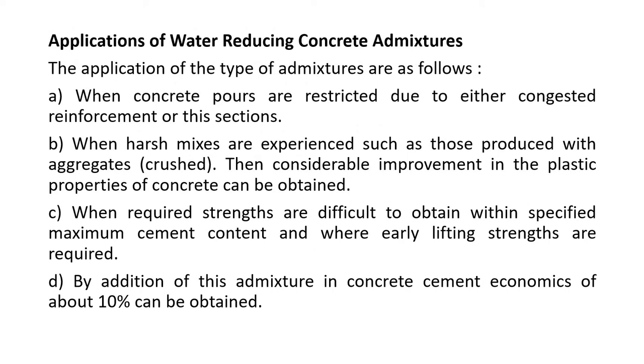Applications of water reducing concrete admixtures. The applications of this type of admixtures are as follows. When concrete placing is restricted due to congested reinforcement or thin sections, when harsh mixes are experienced, such as those produced with angular aggregates, then considerable improvement in the plastic properties of concrete can be obtained.